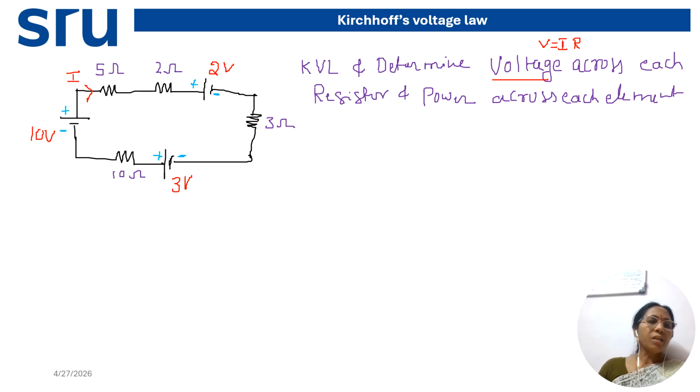Okay, so first let me write the voltages, later we will write voltage across resistances. See here, minus to plus. Here I am writing all the voltages first. Let me take another color. So first voltage source is 10, so that is plus 10. Then next, voltage drop across resistances, just now we discussed with this direction, this is minus 5 into I.